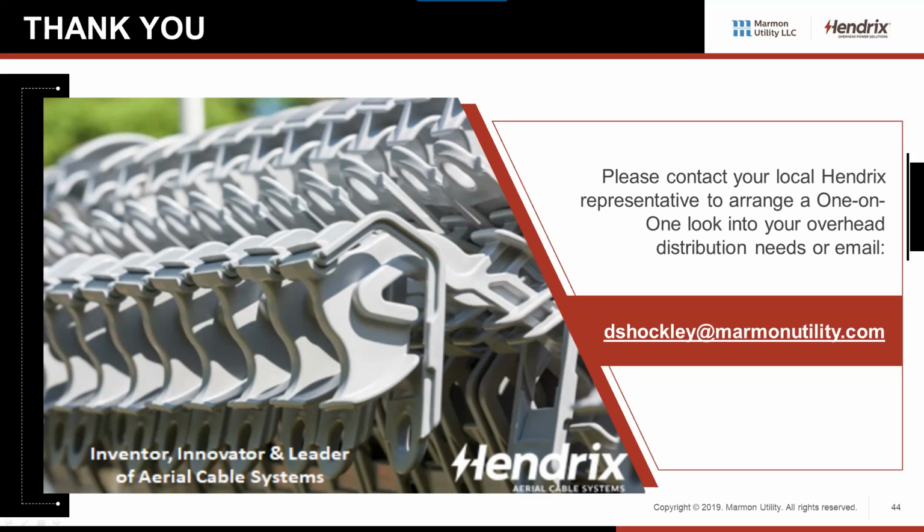What our recommendation is, every 24 inches, you want 3 of the 4 wires covered. So if you expose one of the phase conductors, we recommend you cover up the messenger. And then you'll spread out the taps on the phases by 24 inches along the line. It's kind of hard for me to describe over the phone, but so that's for taps.